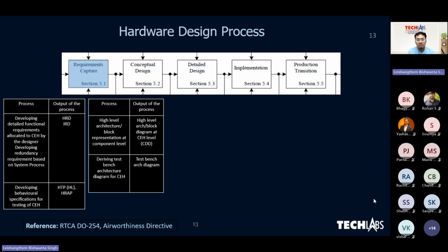So what happened in short here is whatever requirements you have documented during your planning process, both functional, safety, and the other related requirements, you will be capturing them in the requirement capture process. All the requirements should be linked to the next level of requirement or to the next level of your design lifecycle data. We'll talk more about the lifecycle data in a later slide also. Once you do this requirement capture process, you will be getting your output in the form of document or design lifecycle data. That's what we say as an official term for DO-254.